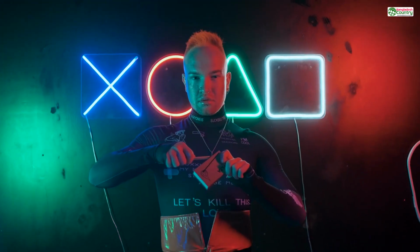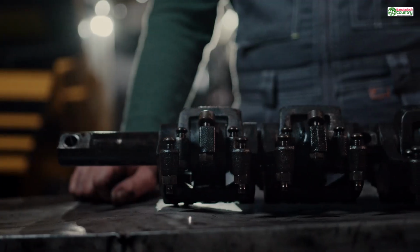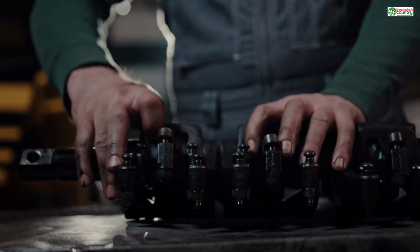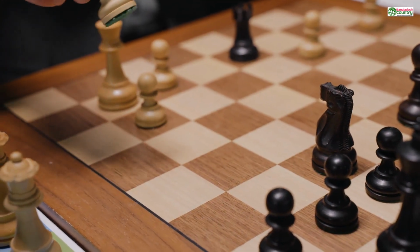It will print faster, use less material, be significantly cheaper, and the final part will be stronger and cleaner. By simply rotating the part before you even upload it, you've completely changed the game. This is the strategic thinking you need to apply. Look at your model. Turn it around in your 3D software. Which orientation presents the fewest steep overhangs?